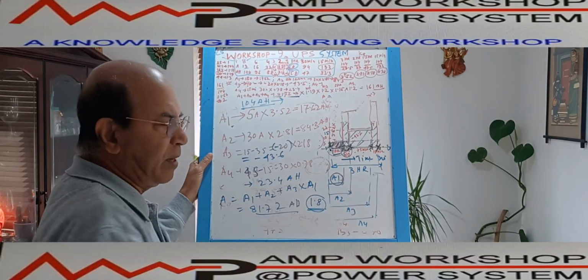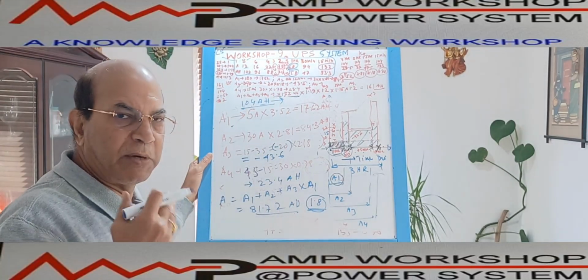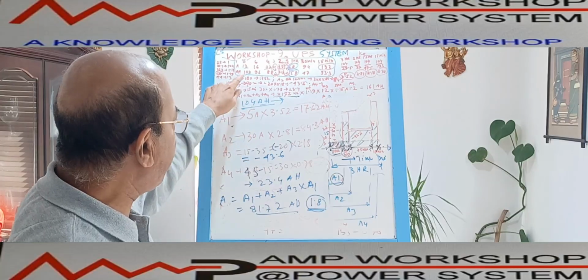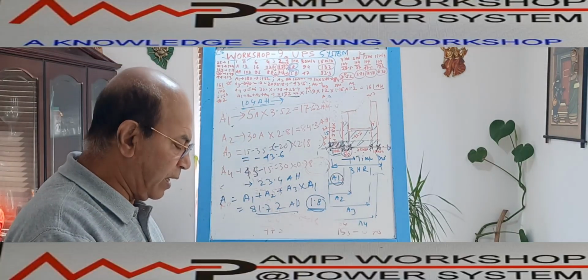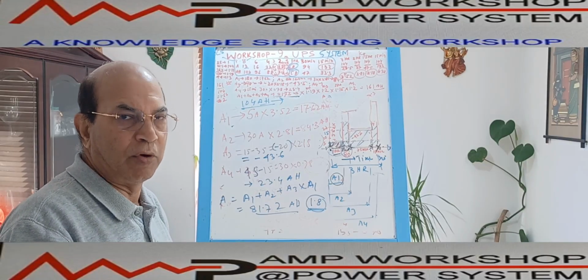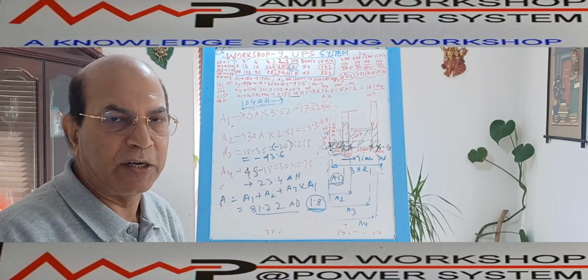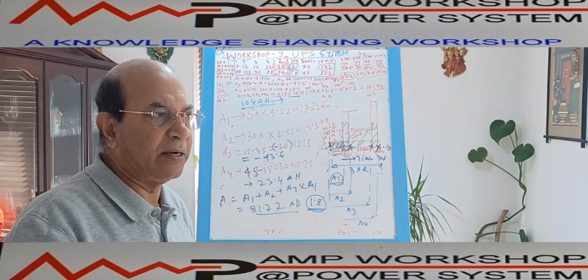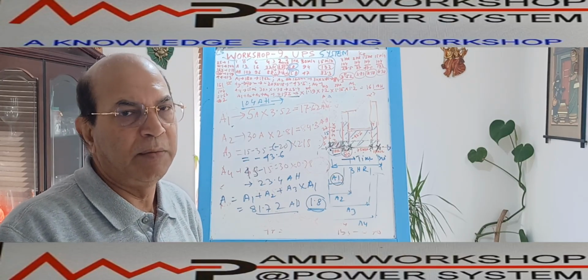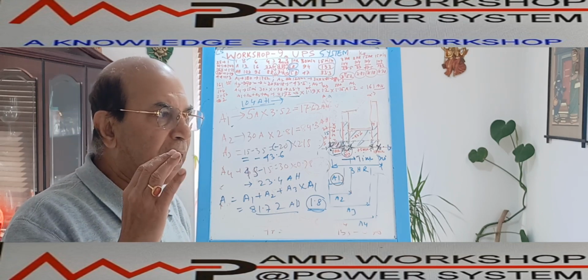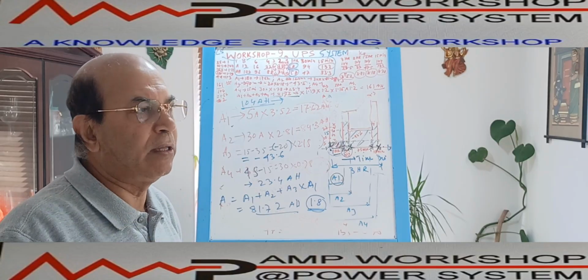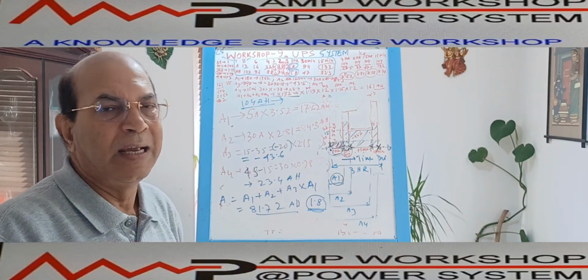We have to refer to our video number 79, where we discussed all these points. Normally for a standard battery, the capacity mentioned for 8 hours is considered at an end voltage of 0 volt. But we cannot discharge the battery to 0 volt, because then what will happen? Inverter input voltage will be 0, and the inverter will not work. So we do not allow the battery to discharge fully. We discharge the battery up to the point where the voltage is maintained up to our requirement.